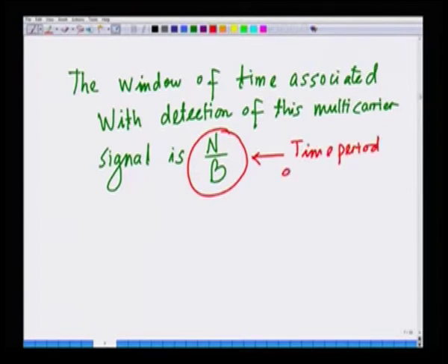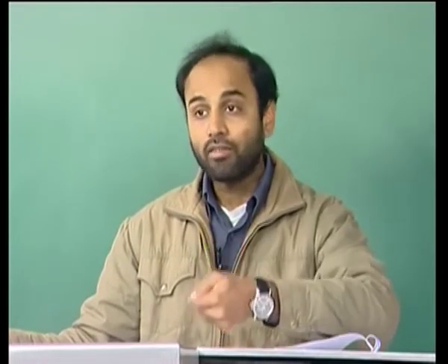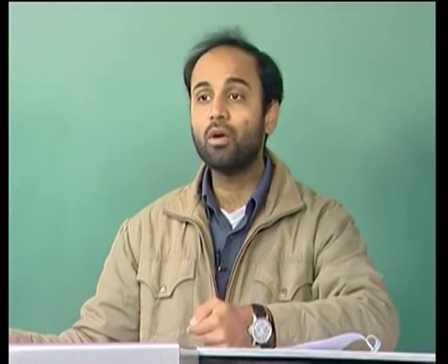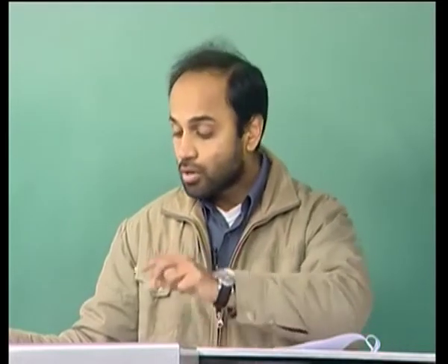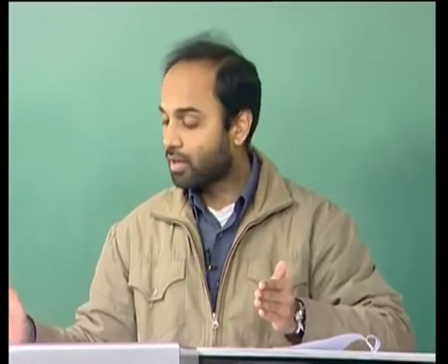This also we said is the fundamental period associated with the subcarrier, that is, the subcarrier fundamental frequency is B over N. The fundamental period is 1 over the fundamental frequency, that is 1 over B over N, which is nothing but N over B. So, this is the time period of integration, which is also the time period of the observation symbol. Now we have something interesting.